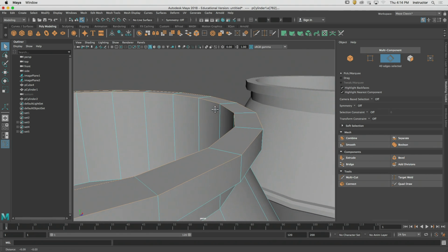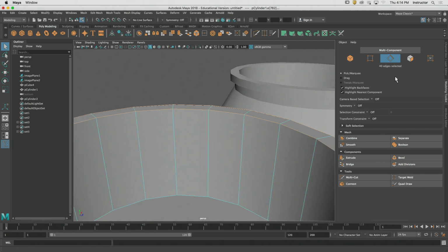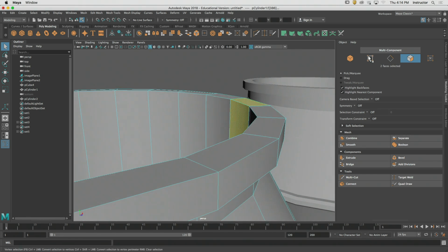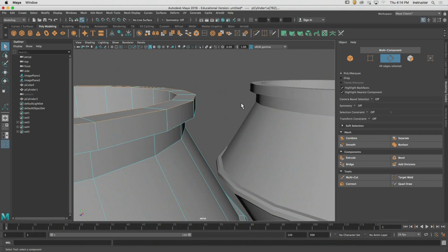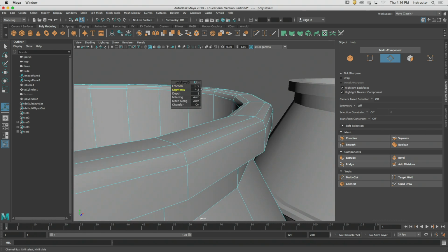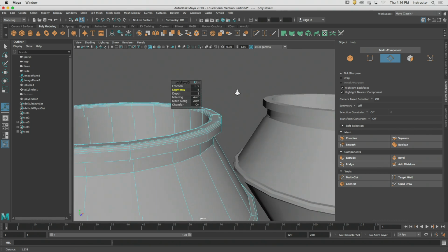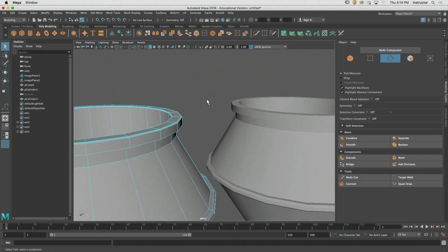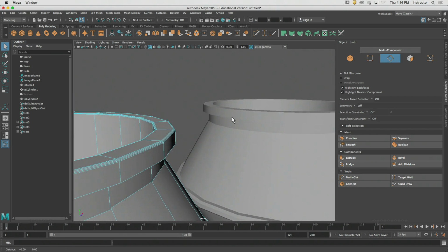Every plane change, okay, and this is a plane change because we're going from this plane to that plane, okay. Every plane change needs to have a small, simple little radius on it, okay. There's a couple reasons why, and they don't need to be anything super incredibly detailed. We don't need to have a zillion segments on them, nor do they have to be incredibly big, okay? But they need to be there.